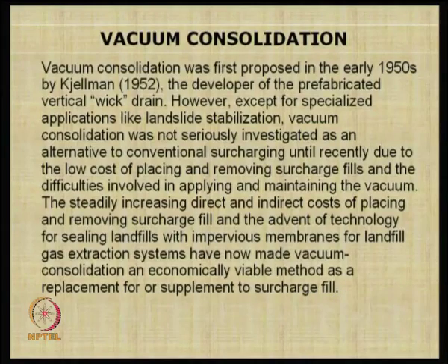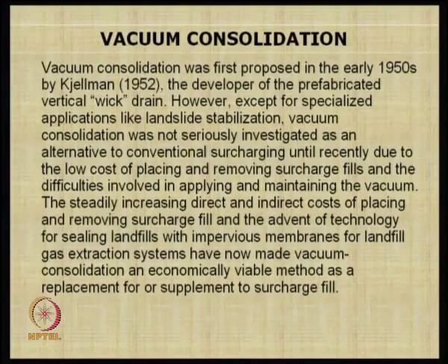Another important point that I would like to indicate here is that there is another technique called vacuum consolidation. Vacuum consolidation is something people proposed in 1952, where you create a vacuum. The advantage of the vacuum is that you try to remove all the air present, even in saturated soil, and if you create a vacuum, an accelerated drainage takes place.